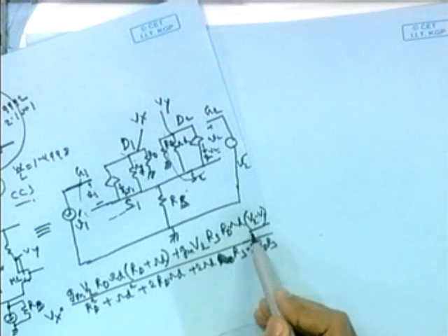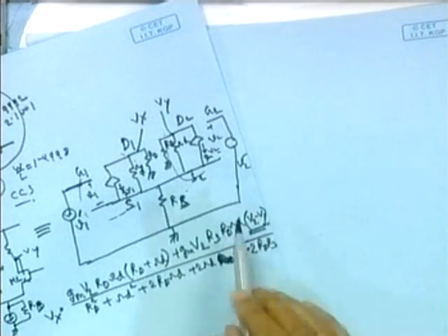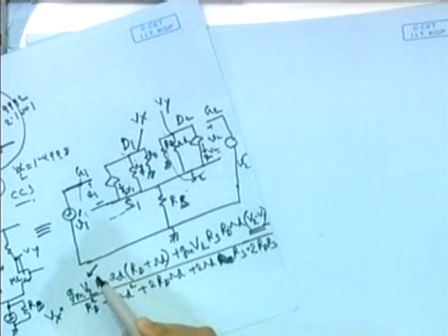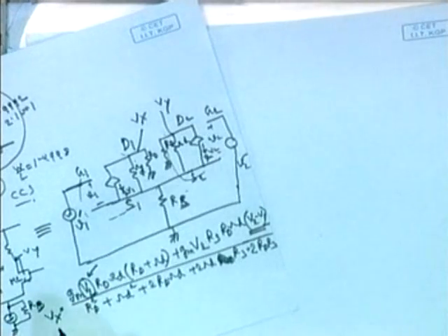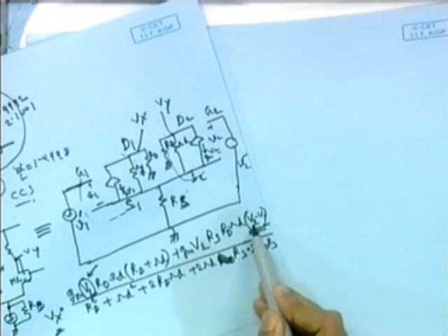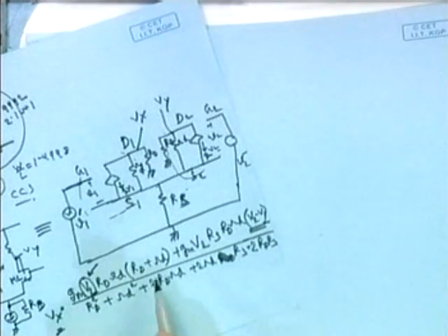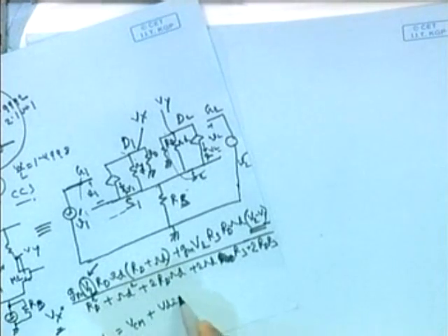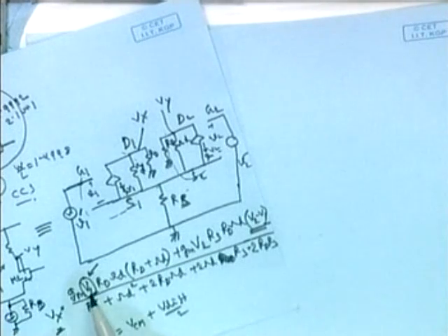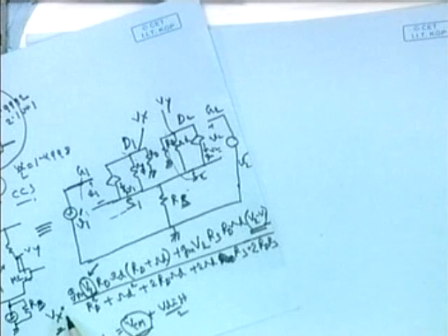Now see, this is our differential input V2 minus V1 or V1 minus V2, but the main culprit is here, this V2. So output contains V2 input term, which is not with other terms, I mean such a V2 minus V1 or V1 minus V2 like fashion. And I have already told that we can express V2 or any input as a sum of VCM plus VDIF by 2. So this V2 we can express like this. So input VCM, and mind you, this is input VCM. So some fraction of input VCM is coming at the output.